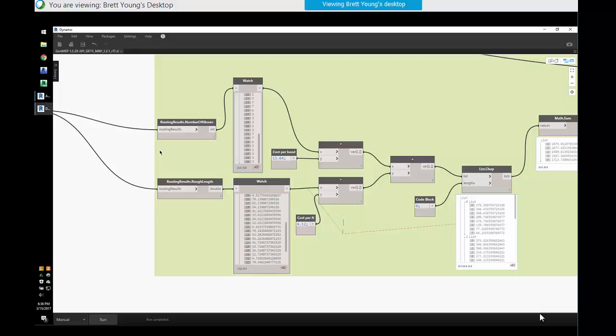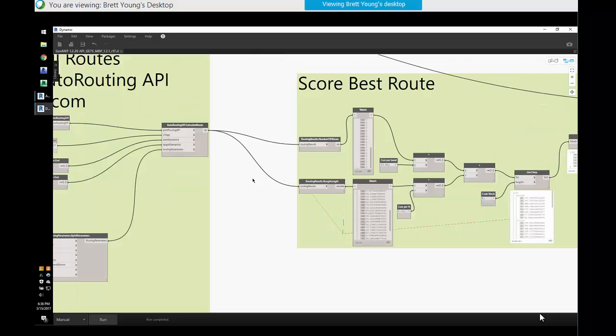Right. Test 4 aspect ratios of that duct against the same 8 routes at the same time and cross-multiply those options, and you have 200 different solutions you're going to work on. How do you figure out what the best of those 200 options were? And so you can use Dynamo to do that. Right. You combine it with the auto routing and do aspect ratio testing along with a scoring method to come up with the best solution. Right. And that script wouldn't look much different from what Ben has written today.